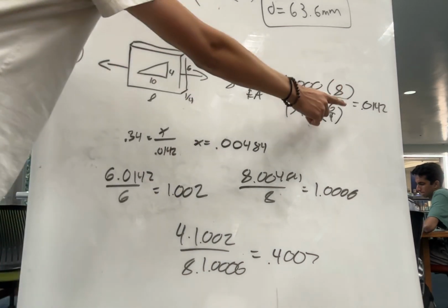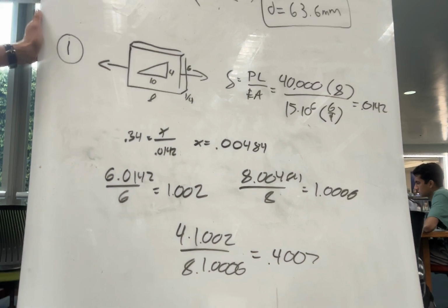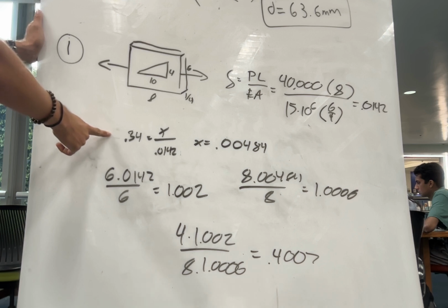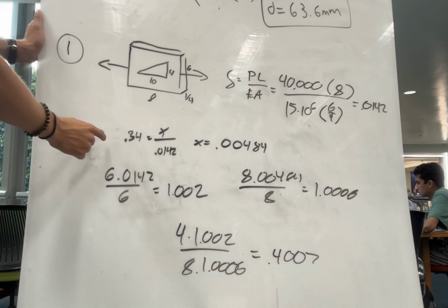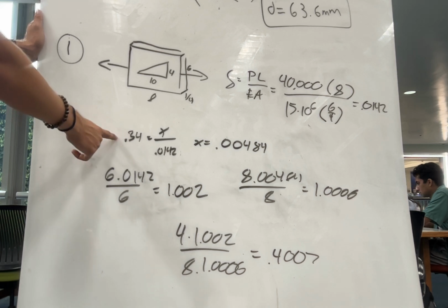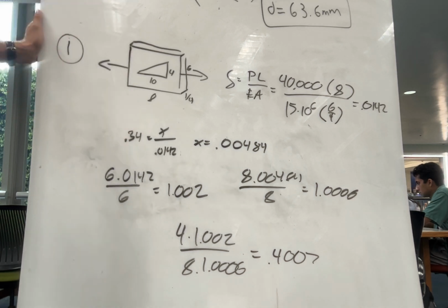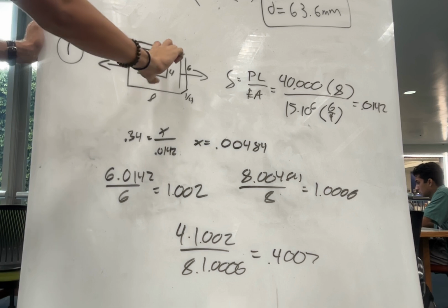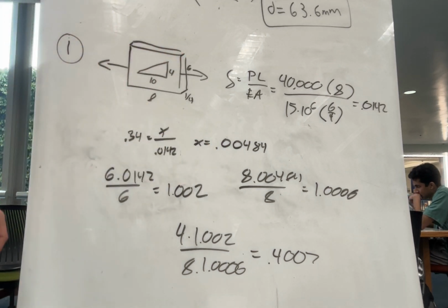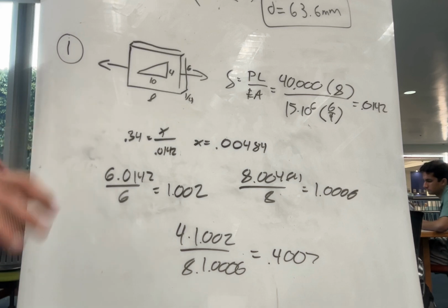And then we're going to get a displacement value, which is how much the length has changed. And then we can use Poisson's ratio, which they gave us, equal to 0.34, to find the other component, how much the height is changing, and we're going to get that number right there. I believe these are in inches, by the way. I forgot to write the units, my mistake.